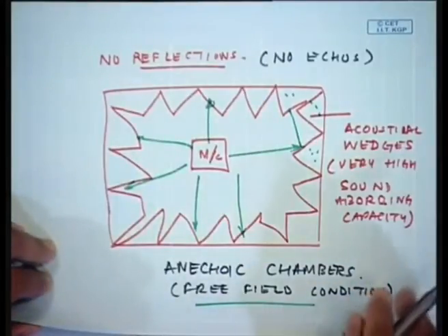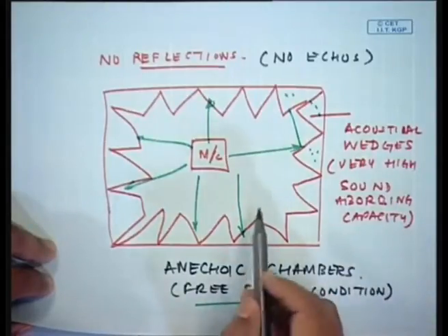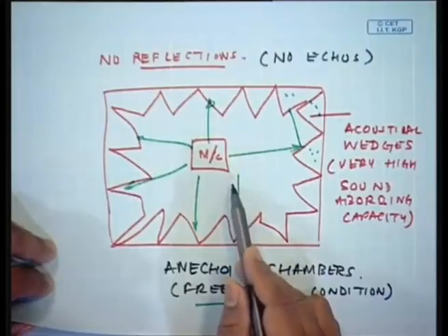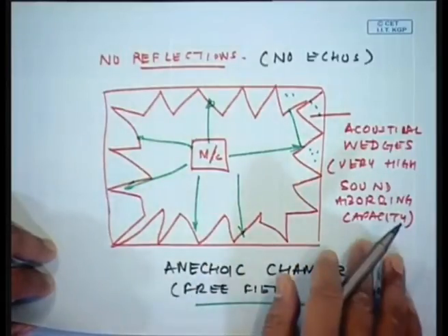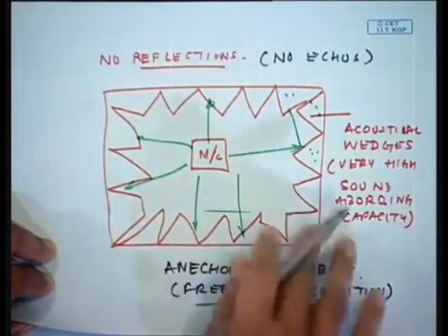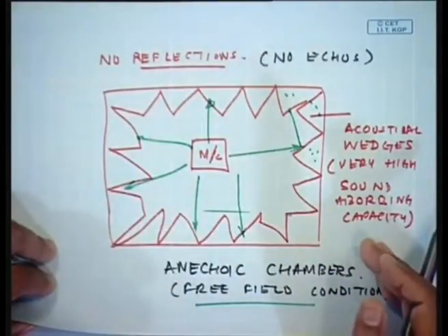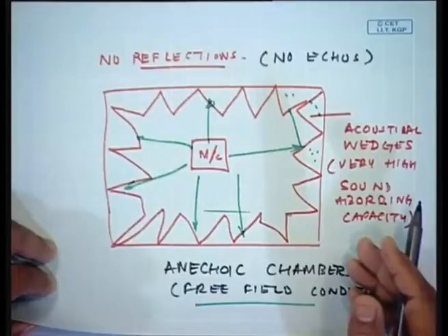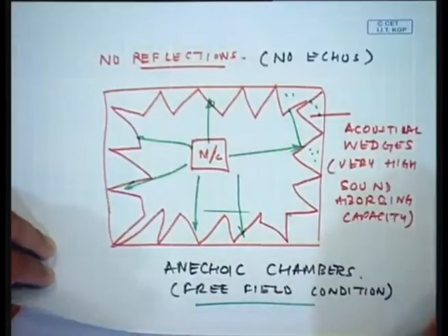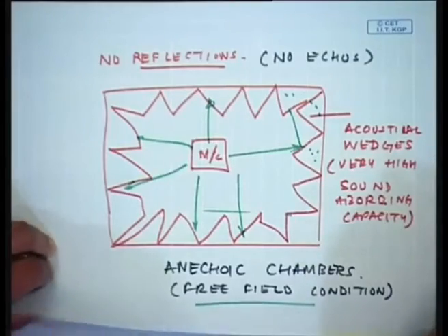Okay. So, when we do the noise leveling of a product or want to find out the sound radiated by the machine, we usually test them in such anechoic chambers. Okay. In fact, people test vehicles in such chambers. They can put a grating here and then they can drive in a vehicle, rev it up and measure the sound pressure level radiated by it. In fact, the same phenomenon is used in the electromagnetic absorption of radars, and such chambers are also there in the radar and communication centers, where they test antennas as well.